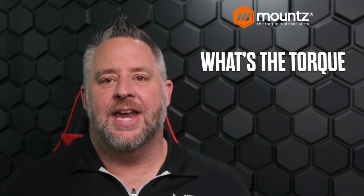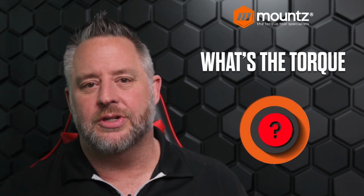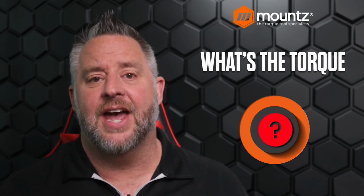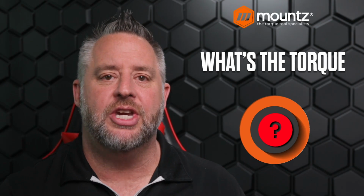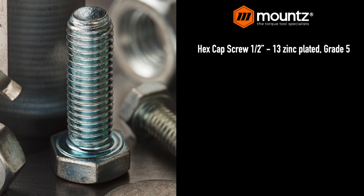So let's go ahead and do an exercise where we want to establish a torque value based on the clamp load, or clamp force, that we want to achieve. In this case, we have a 1/2 inch hex cap screw, zinc plated, grade number 5. And we know we want to achieve about 9,000 pounds of force to be able to hold our components together.